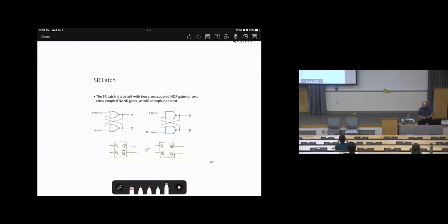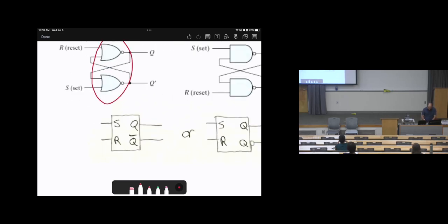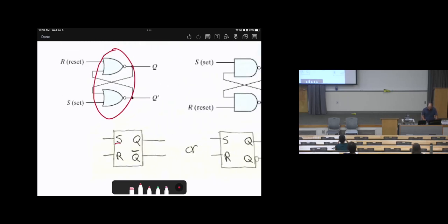Okay, so again, for active high and active low SR latch, we can draw it this way. As a shortcut, instead of keep drawing these two gates, we can make a small box like this. Here is the input S, input R, here is output Q, here is output Q bar. This box has been created on purpose, so we don't want every time to draw two NAND gates or two NOR gates as we see here.